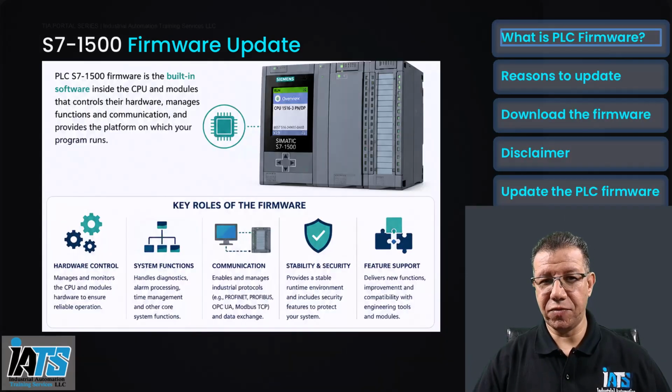What is a PLC firmware? Under the hood of the PLC, the firmware acts like an operating system, controlling the PLC's internal operations, the system's built-in functions, and running the user program. The firmware enables the PLC to handle hardware modules, support timed and interrupt-driven operations in the user program, process diagnostics and alarms, and communicate with engineering tools and other devices.